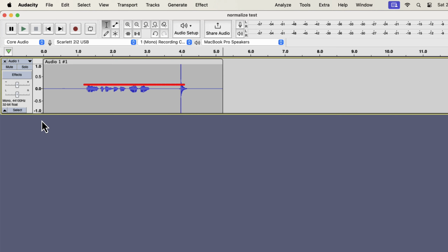If I draw a line on the quieter level and the loudest level, we will get a gap. This gap is called the dynamic range. The bigger this gap is, the more difference between louder talks and softer talks. A large dynamic range like this can make the listening experience poor. Soft talks may be too difficult to listen to, and the loudest talks may be too loud. To mitigate the issue, we have to decrease the dynamic range.